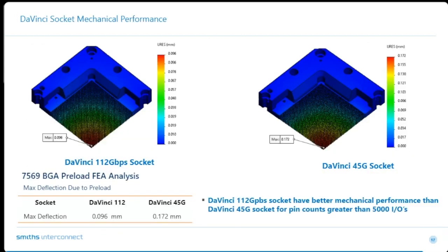So assuming we can meet the electrical targets during the mechanical design phase, we'll run FEA and ensure the socket strength meets the deflection requirements. And we can make any changes if necessary. The mechanical designer can shore up the body design. We've got some challenging PCB mounting due to high trace routing out. Sometimes we're limited on mounting screws, but we've done some pretty large devices, and so far the insulated metal body has proven to be very robust, and we see no issues with deflection.